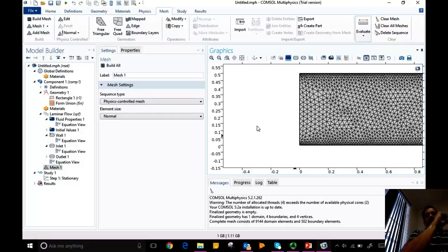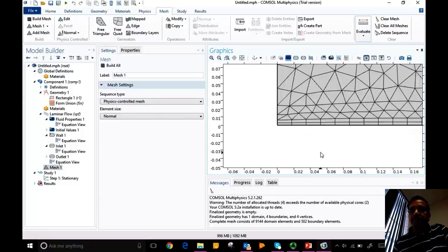Question? Zoom in one more time, on the wall. See, that's what I'm saying. Just close to the wall, the shape is different. In the center, we have triangular, and close to the wall, we have rectangular shapes. Yeah, right. So this is what they call a structured mesh. A structured mesh essentially says that they are all connected in sequence, so I need to know only the coordinate locations. You will understand this when I actually show the discretization process for a differential equation.